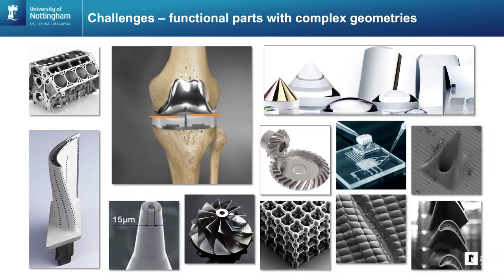So what are we addressing? We're addressing surface measurement. Now, this could be the overall shape of a part. It could be the fine scale texture, and we're going to concentrate on that fine scale texture today. But the problem is that components are becoming more and more complex in terms of form and texture, and this makes them much more difficult to measure. We have very high slope angles, very complex structures, and many occlusions which make it very difficult to measure using optical and or contact techniques.